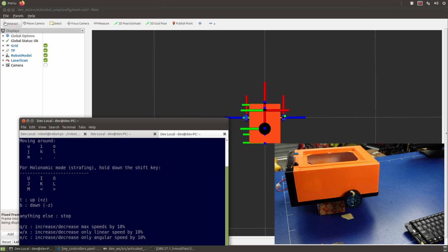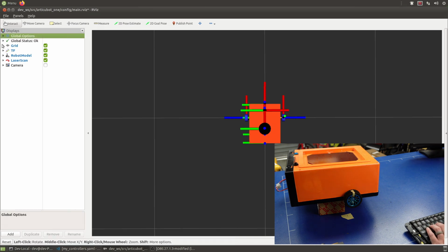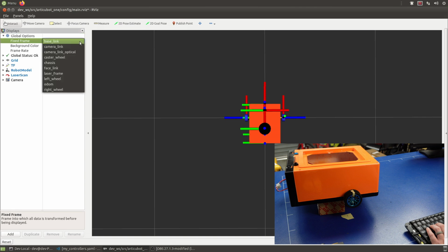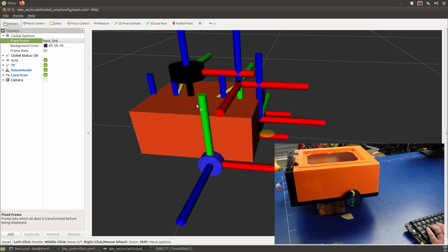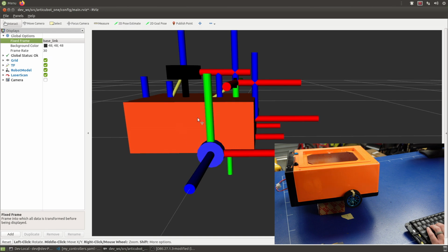This is just a quick follow-up on some of those issues I was talking about before that was giving me poor odometry, and how you can go about fixing those yourself. So first up, we're going to check that the encoders are set up correctly. I've stuck a piece of tape on the wheel pointing upwards. Now what we want to do is in RViz swap to the base link as our fixed frame, so that the robot's going to stay in the same position. And now we can see how this y-axis is pointing upwards at the moment.